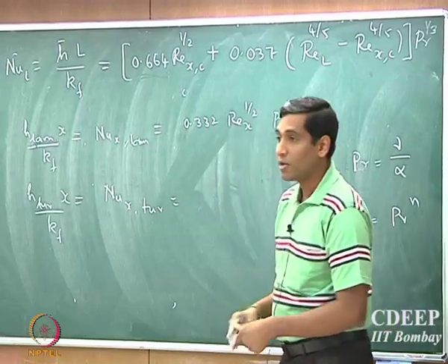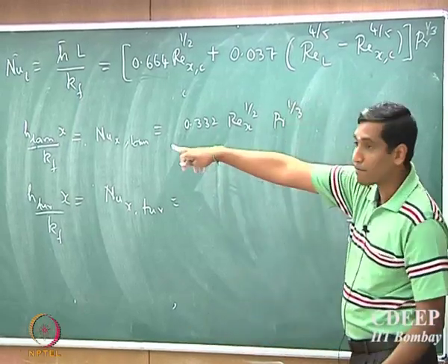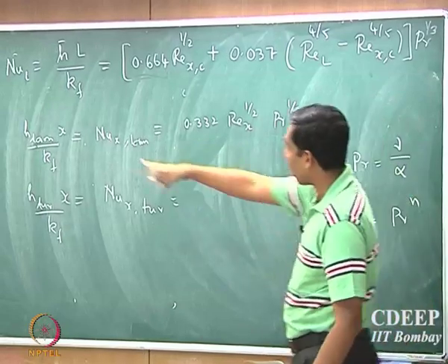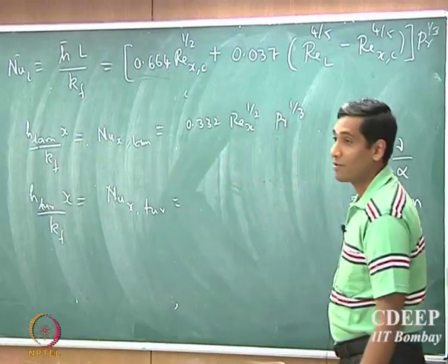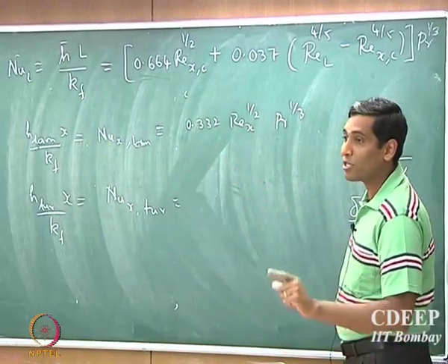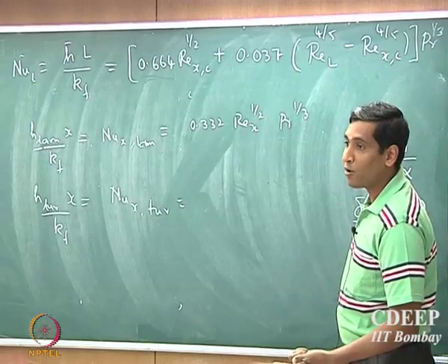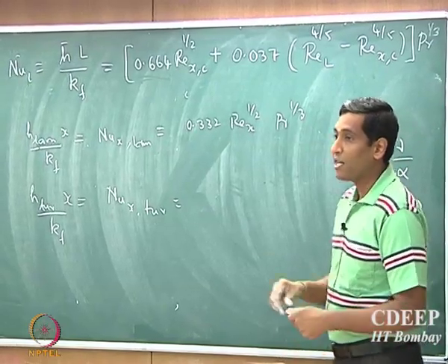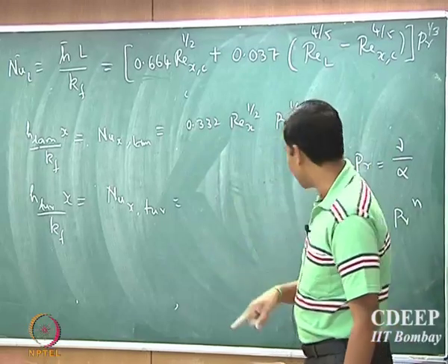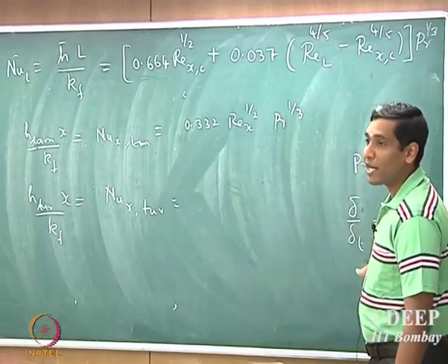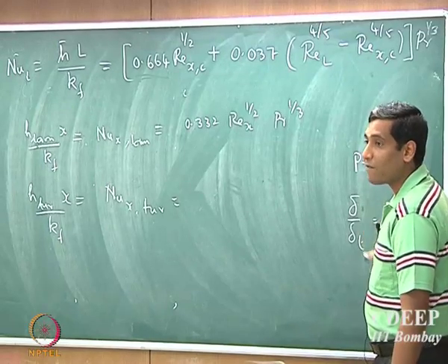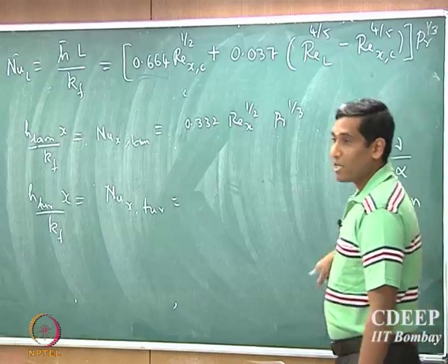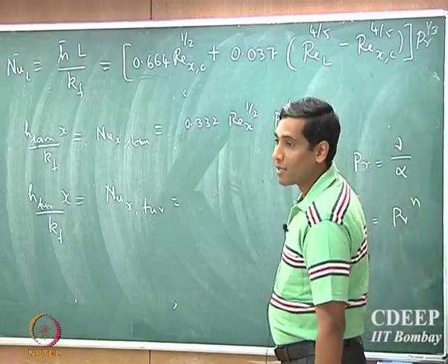Yeah, that's true. So it turns out for the flat plate case it's the same. So note that it's not just the hydrodynamic boundary layer which changes. This is the ratio. Be careful, it's a ratio. It's both the hydrodynamic and the thermal boundary layer actually that is changing. Now when it comes to Prandtl number less than 0.6, the variations that you get in turbulent flow are very different. So you have to be careful how it is defined. This problem comes only when Prandtl number is less than 0.6.